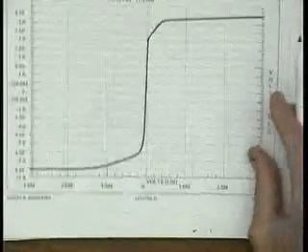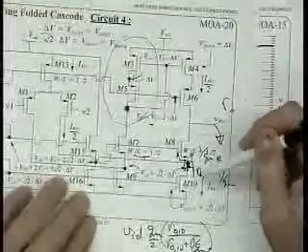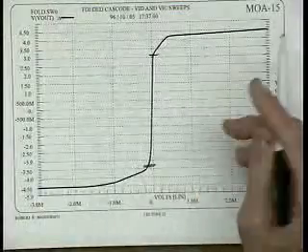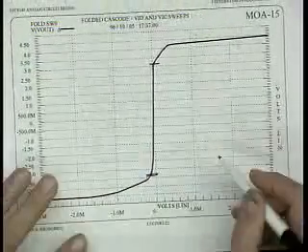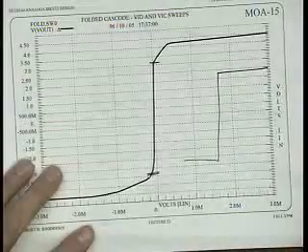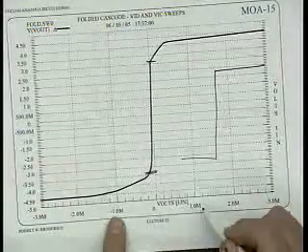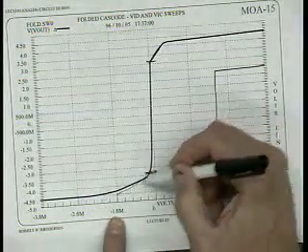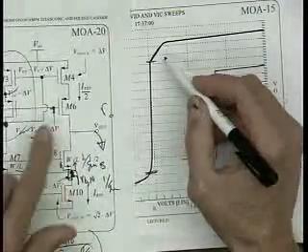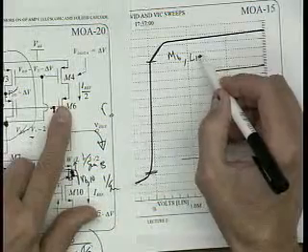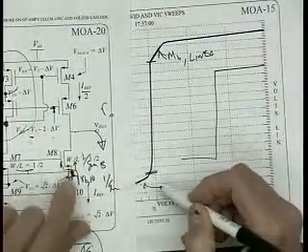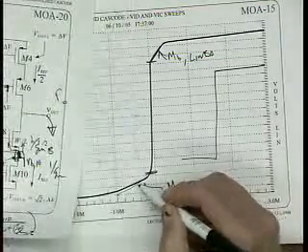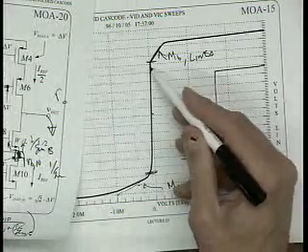And you've got to watch out. On these kinds of stages, going up and down, here's the really high gain region. If you look at it not on the right scale, it'll look like a sharp line, because the gain's so high. But if you blow it up, now I'm going between plus and minus 1 millivolt, you'll begin to see this is where that upper transistor is going into linear region. This is where M6 is going linear, right here, and this is where M8 is going linear, and the gain's dropping. Here's where everything's in saturation. Here's where the gain's the highest.